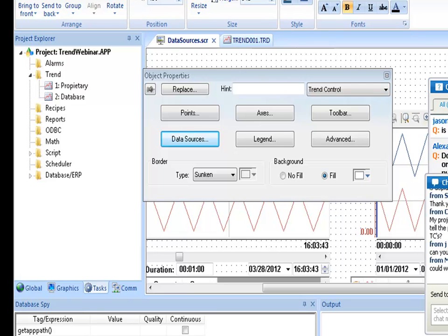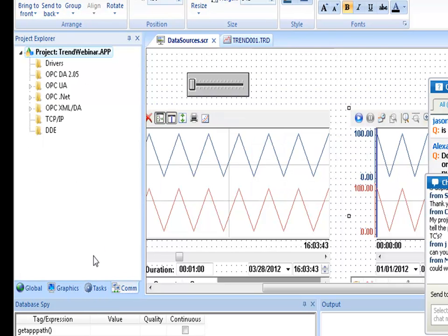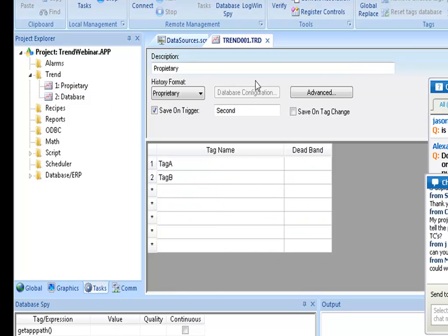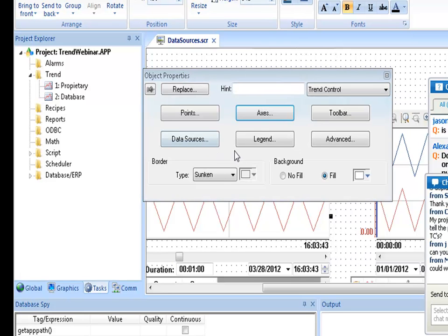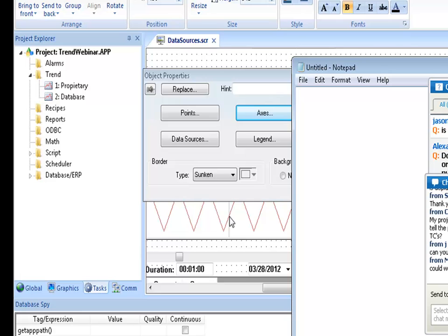One question here is a project that monitors 40 thermocouples. Is there a way you can tell the program which thermocouples to monitor and record from the 40 thermocouples? My recommendation would be to configure a trend worksheet with the 40 thermocouples. And on the trend control, just use the interface to add or remove pens for the thermocouples that should be visualized and save it as a profile, just like I did here during the webinar. But if you have more specific questions, just send an email to me or call me later. My email is fabio.souza@indusoft.com, and I'll be happy to work with you in your specific project.